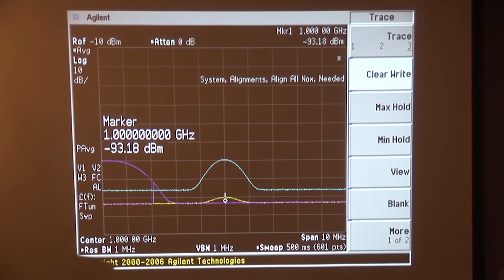I'm going to turn this off momentarily. Put the little 16 dB attenuator in between the output of the amplifier and the spectrum analyzer input, just introducing that loss. And so this in effect, putting this attenuator in here is going to effectively reduce the gain of this stage.